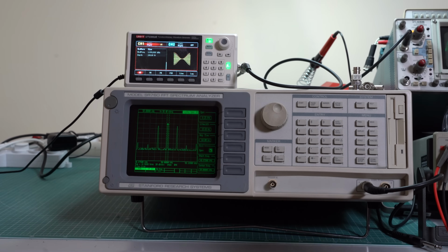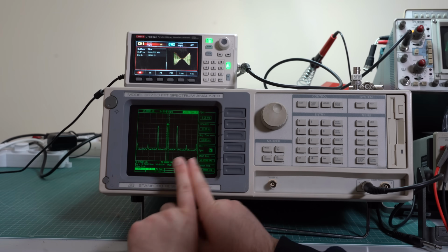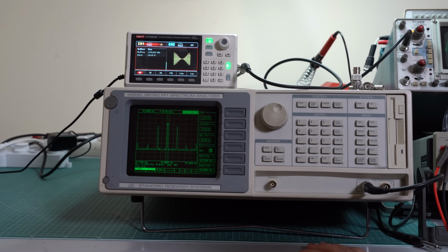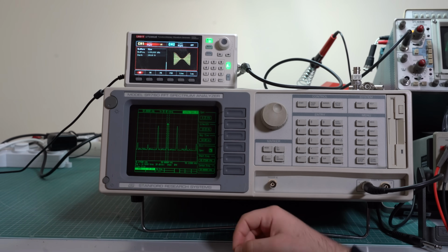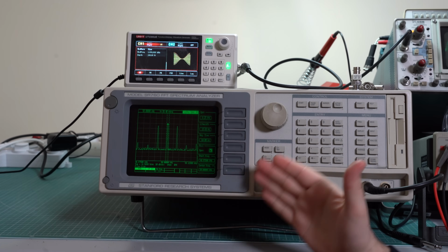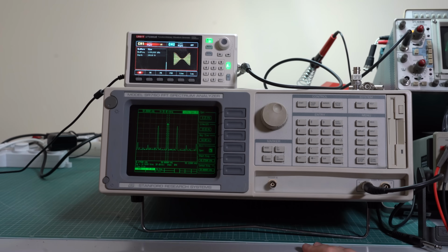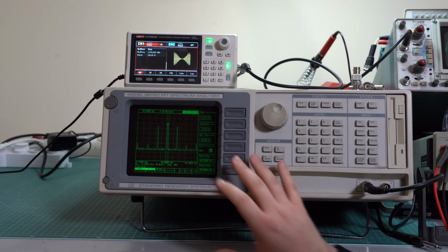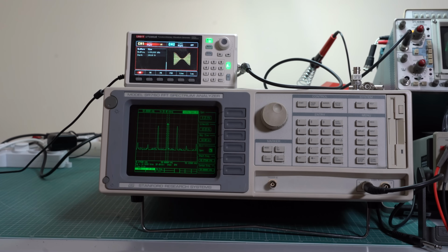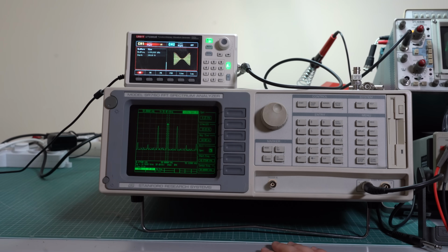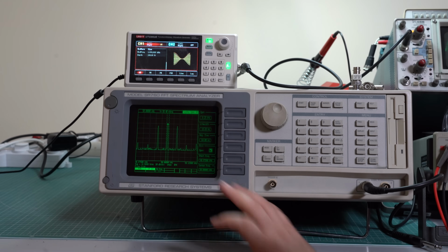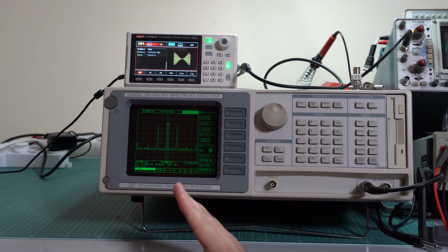Another important setting of the horizontal axis is the resolution bandwidth. The resolution bandwidth is basically how narrow the filter that analyzes the signal is. In this case, this is a digital instrument, so it doesn't really have an analog filter that sweeps from the start frequency all the way to the stop frequency, because this is done using digital signal processing. However, this instrument does have an equivalent resolution bandwidth, and that resolution bandwidth is the span divided by 400. That's because I think this instrument uses 400 FFT bins. On other instruments, especially analog instruments, this is something that you can set using a knob. In this case, this is basically a fixed ratio from our span.